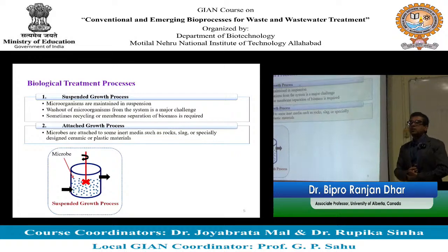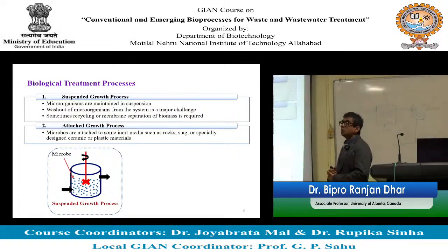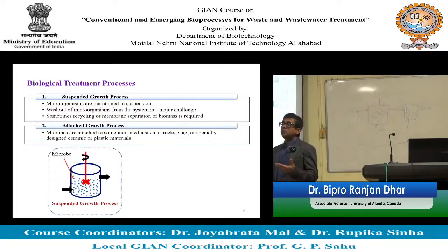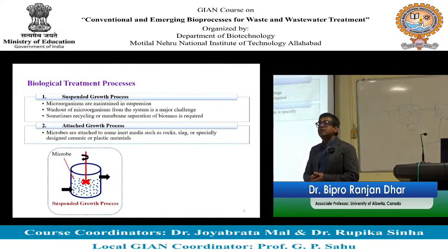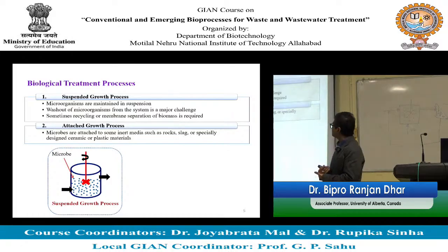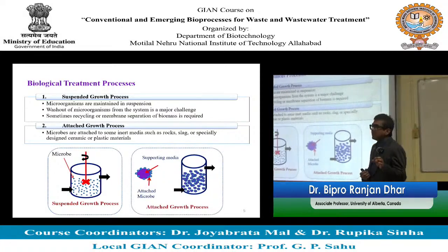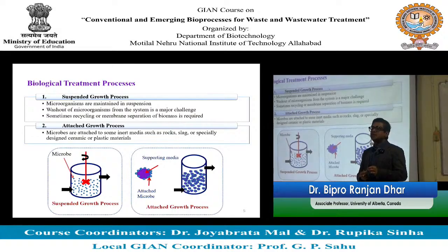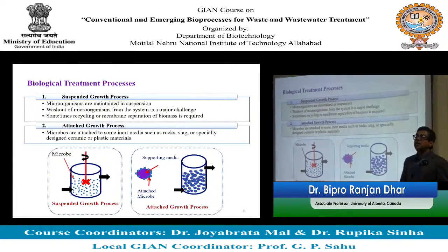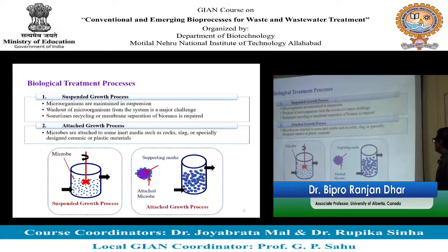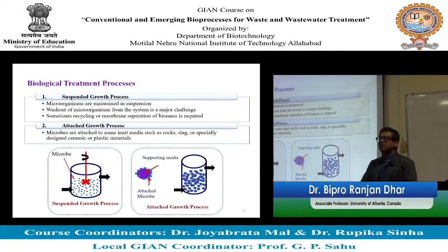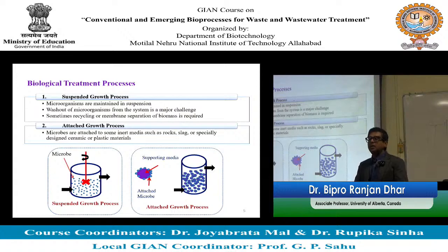Another approach that we can use is the attached growth process, which allows us to overcome the washout that we often face with suspended growth processes. How does that process work? Instead of keeping the microbes in suspension, we can have different types of inert media, such as plastic media or some other biomaterial, where we can attach the biomass. So it is more like a biofilm system.